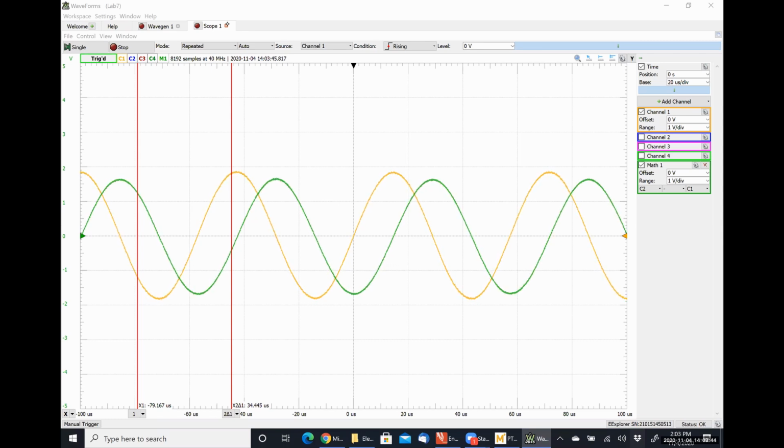So we are asked from the graph, does current lead or lag the voltage across the inductor? So if we look at two peaks which are close together, is the yellow curve first in time or second in time? It's first, right?